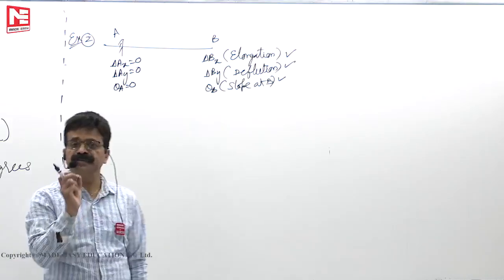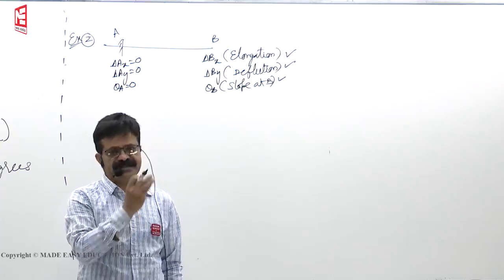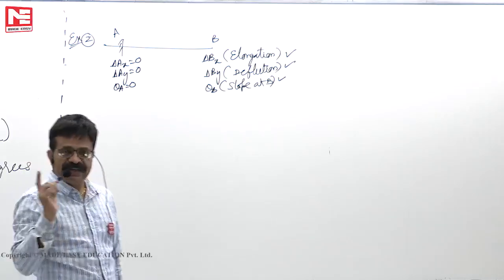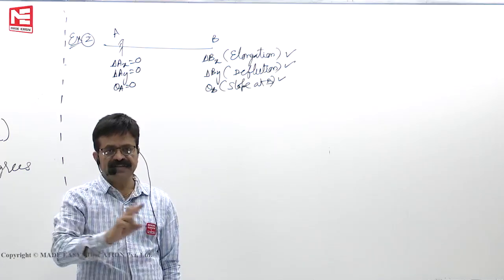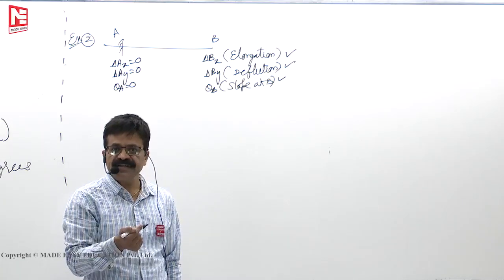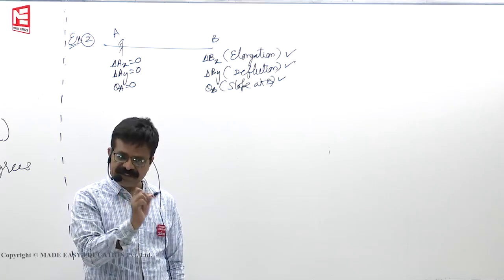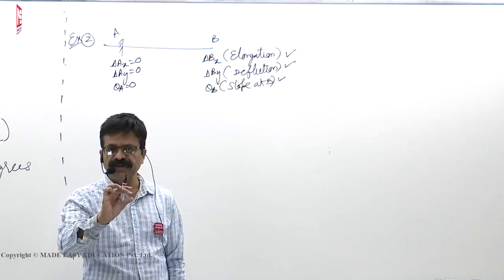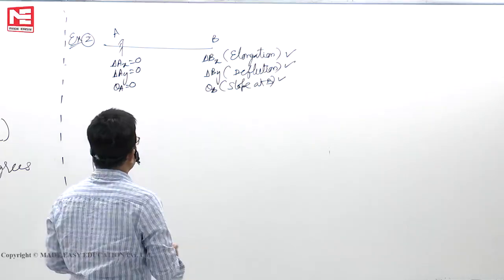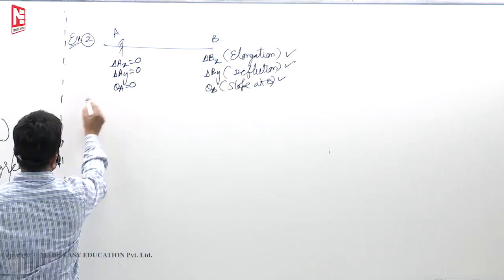So, two cases are possible in beams and frames, whether they are axially extensible or axially inextensible. Depending on that, two options can be given. Any member if axially rigid does not mean that flexurally rigid also. They have to specify. Flexurally rigid means EI is infinity. Axially rigid means AE is infinity. Whatever they ask you to take as infinity, only that we have to take, other we should not take. That is possible to happen, we should assume. Okay. So, such cases, now you see dk when extensible.